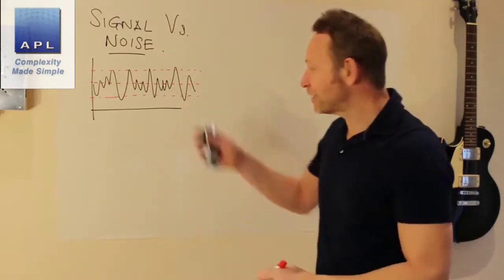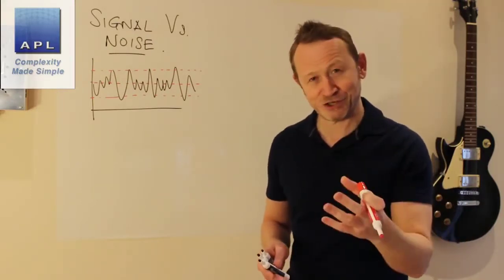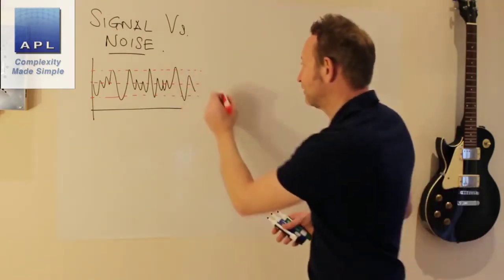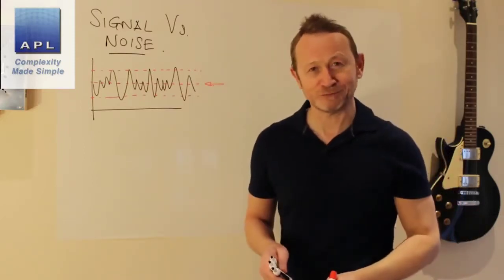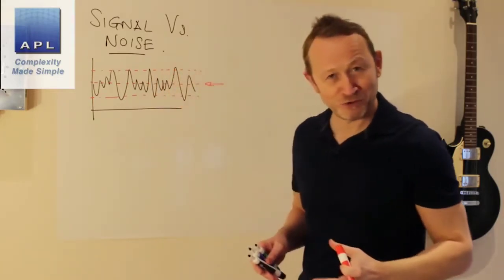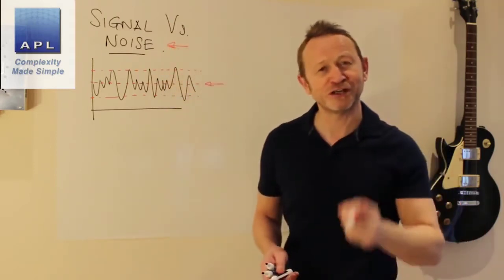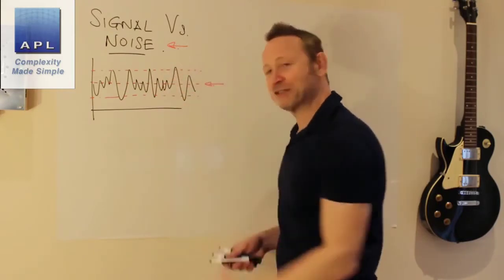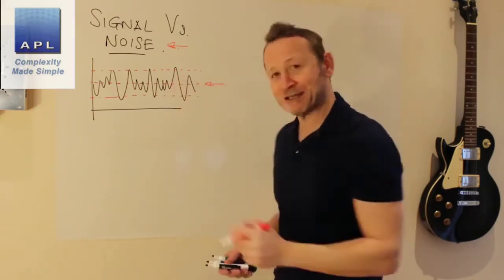Okay, now then, let's look at this thing. Is my problem the ability to hit the center? To hit the target? Actually, no. The center of my results is sitting right where I need it to be, slap on the nominal. My problem is that I have too much spread around that setting. In other words, I have a problem with noise. I don't have a problem with the signal. The signal is the middle. I've got the middle sitting smack on target. So my problem here is with noise.